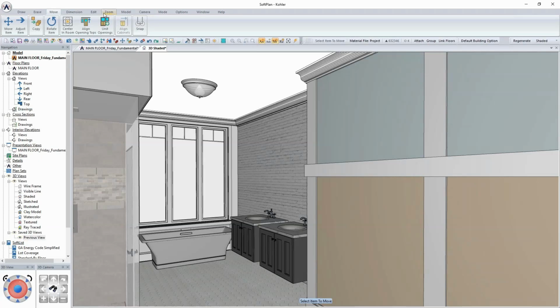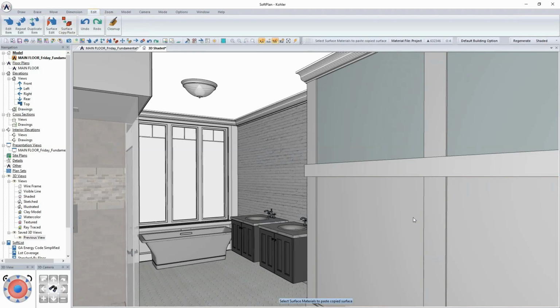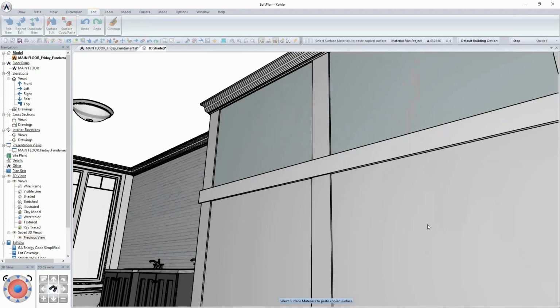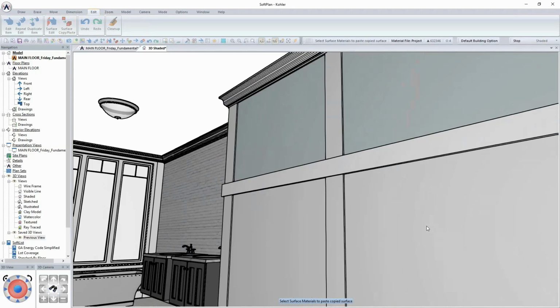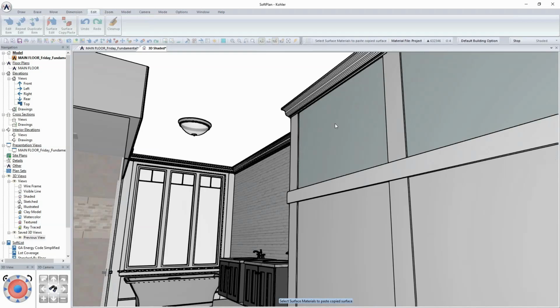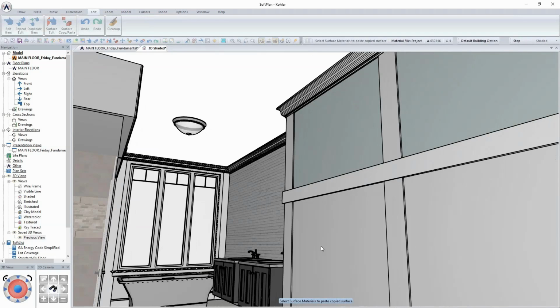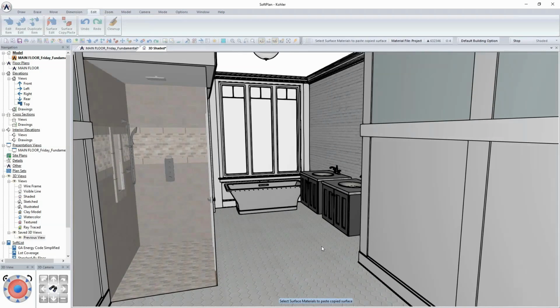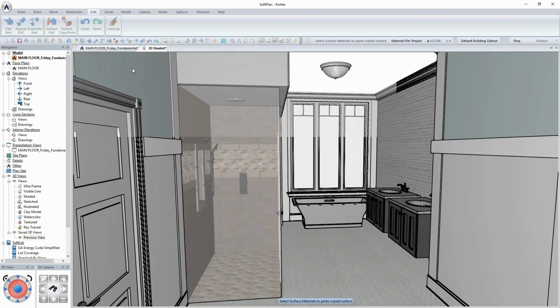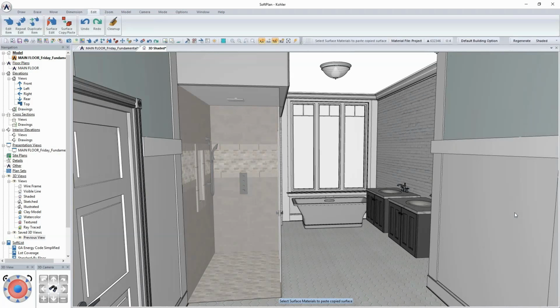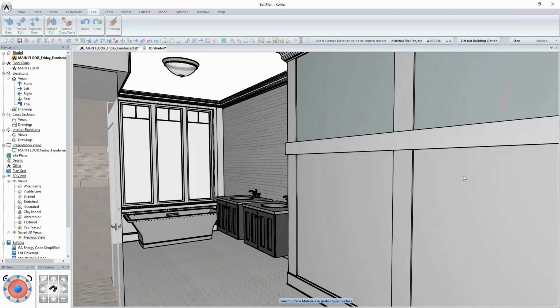And I'll do that. The bottom half of this wall, I'm just going to assign the same white pattern to this. In this case, just simply copy and pasting the white on the bottom half, I now get the blue on the top half because I've modified my wall texture to be offset up X distance. And then the bottom half I will leave as white. And so now what we've got is that lighter blue up top, and then we've got the white almost wainscoting on the bottom half with the trim patterns that are there. All right, so that's how we can get that.